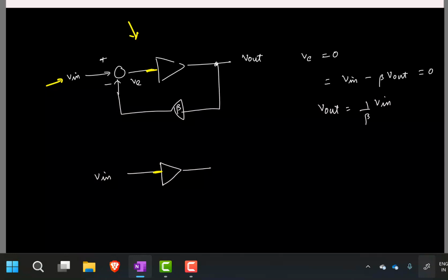Now, if you have a nonlinear system, when do you think the nonlinearity will be more pronounced? When the signal is small or when the signal is large? Large, right? I mean, if it's small signal, it's a linear approximation. At least that makes sense. So if it's large, it is going to be more nonlinear. And you see that in open loop, the signal swings are going to be large. Whereas the moment you put it in closed loop, the negative feedback enforces the error signal to be small. So fundamentally, the amplifier will also be behaving more linearly. Okay.